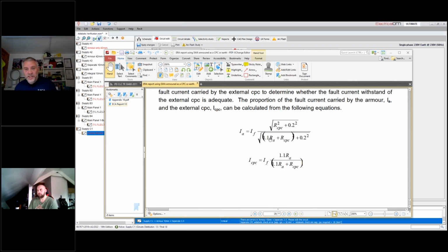Actually, we'll probably jump around the questions here. One asks about cables in containment. If all the cables, like using a 5-core cable, are within the steel containment, you're not going to have those problems. Another asks, if it's an issue with the SWA armouring, what happens if we put this on ladder rack or tray? Does the tray cause a similar magnetic effect? The tray's not there as a protective conductor. We're not using it as a protective conductor in that case.